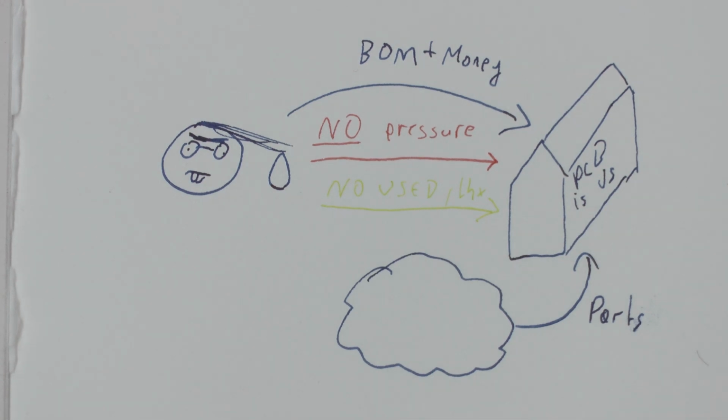And this brings us to the second point. If you are aware of the problem of used components, then obviously you can always tell them, please don't use any used components in my PCB. And as we already discussed, the costed bill of materials allows you to easily identify components where it is likely that we will be dealing with a used component.